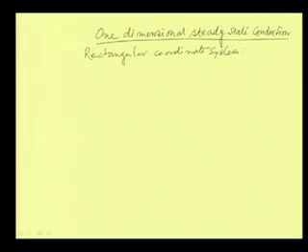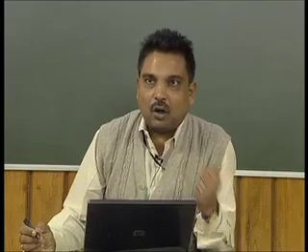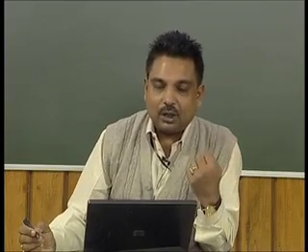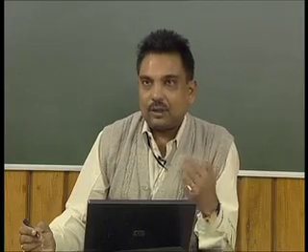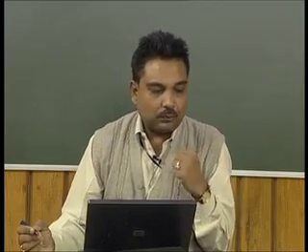To start with, we will discuss a plane wall. Consider a plane wall, and this is the direction of heat conduction. At this point its temperature is, say, T1, and at this point its temperature is T2. Now, in this case we will see from both angles the direct application of the phenomenological law of Fourier, or Fourier first law, and Fourier second law, or Fourier field equation. We will see how to apply this.